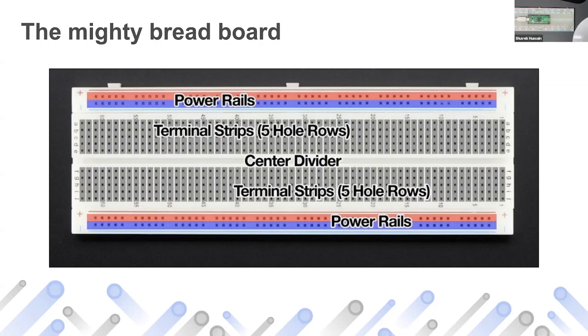You can't. The Raspberry Pi Pico is a microcontroller. It's not a full-fledged system with a CPU and RAM and all that. Microcontrollers generally have CPU, RAM, and flash storage right on the chip. So this chip contains everything: the dual core ARM CPU we spoke about, the RAM, flash, and all the hardware peripherals. So it cannot really run a full-fledged operating system.